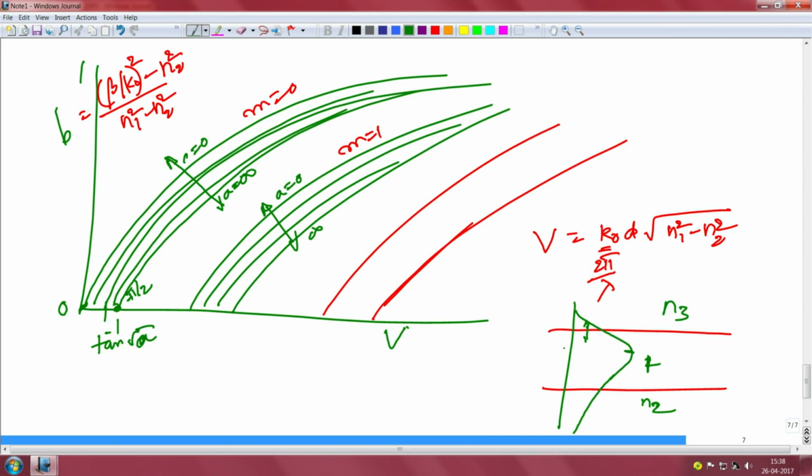We can expect that it is not coinciding in the middle, but somewhere offset towards the air region, and alpha 2 is small, so we can expect a longer trail. So, there is an asymmetry of the exponential trail as well as the oscillatory field. By similar arguments we can note the properties of the next modes.